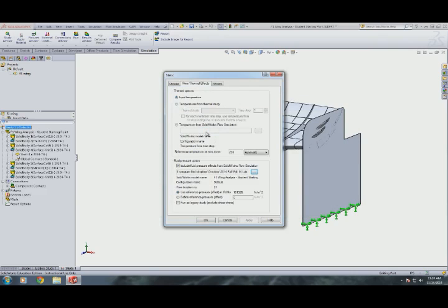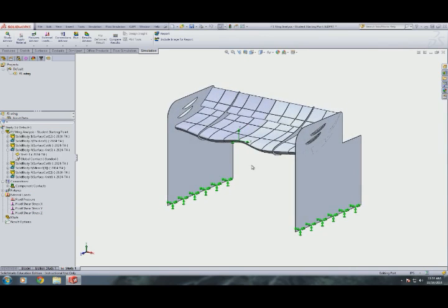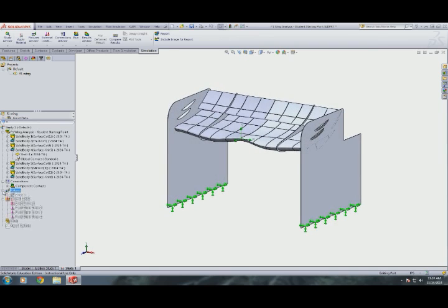Alright, that's it. Hopefully in your case, since you've only run one CFD study, there's only one to worry about. So that's what we need. That looks okay. So that will actually import. If you look underneath loads and expand it, we have the fluid pressure over the whole body. We have fluid shear stress in X, Y, and Z. So that's really slick, to be able to import actual CFD pressure contours. So fixtures fixed on the bottom, pressures on the sides.